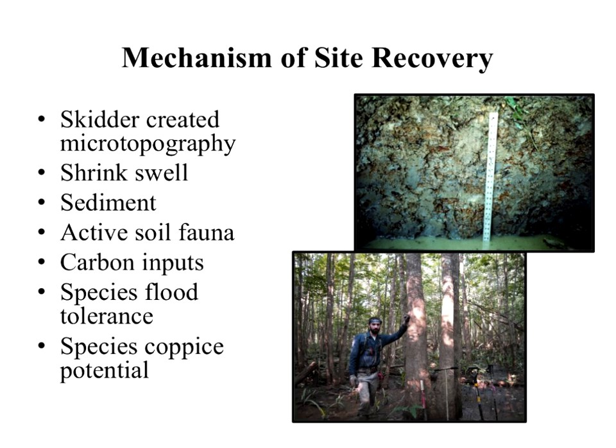Another very important thing on this site was that these had shrink swell soils, and these shrink swell soils recover much more rapidly. When they wet and dry, they shrink and swell, so compaction tends to be naturally negated that way. Another really important factor on this site was we had a lot of sediment being trapped. We had between 10 and 16 inches of sediment trapped on this site over a 23-year period. That much sediment coming in is also going to offset the compaction, because you're bringing in non-compacted, nutrient-rich sediment.